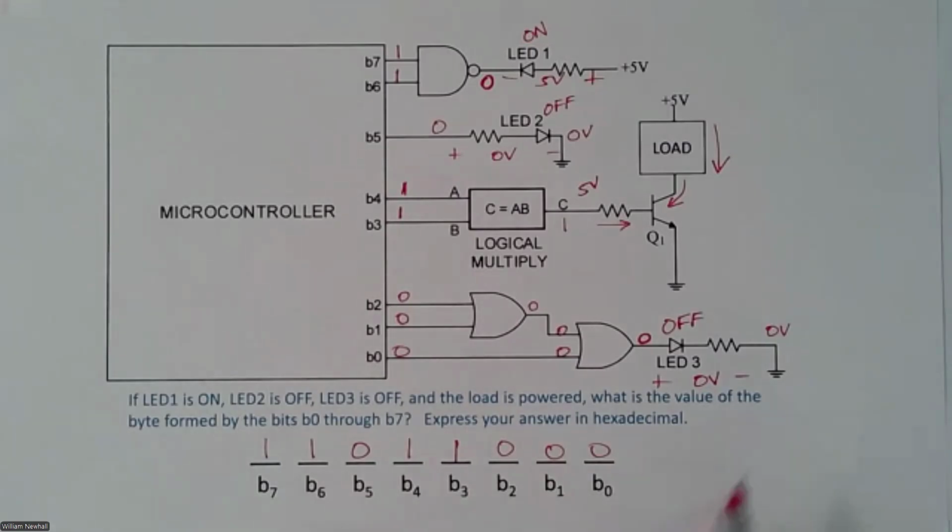Okay, so here's our binary word. This is base 2, 1101 1000. That's binary base 2. And so then to express this value in hex, you start at the radix and imagine it here. There's no radix point shown, but it's going to be all the way on the right if this is just an integer value. So we have 1000. That is an 8 base 10, which is also an 8 base 16.